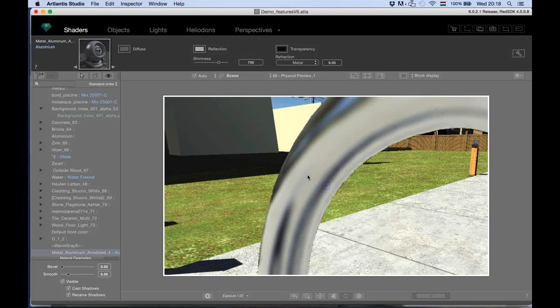The preview generally works in a fast mode. What does it mean? It means that it shortcuts some calculations. So whenever it displays such a metallic railing, instead of 3D reflections, it will go fast and say, okay, I apply a 2D reflection on it. It might seem even shinier here in the preview. Therefore, we need to make Artlantis recalculate, to refresh this preview. And then, when the refresh is done, we will have the real aspect of materials.